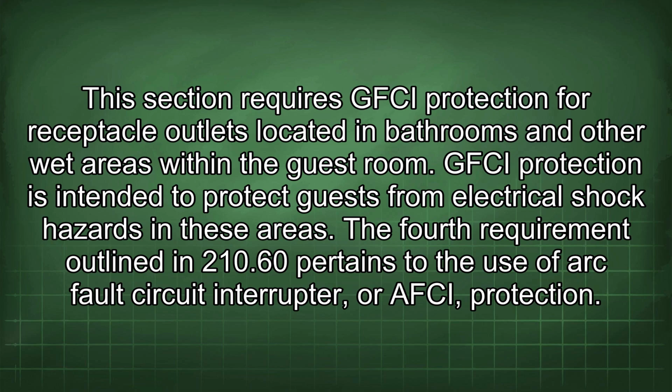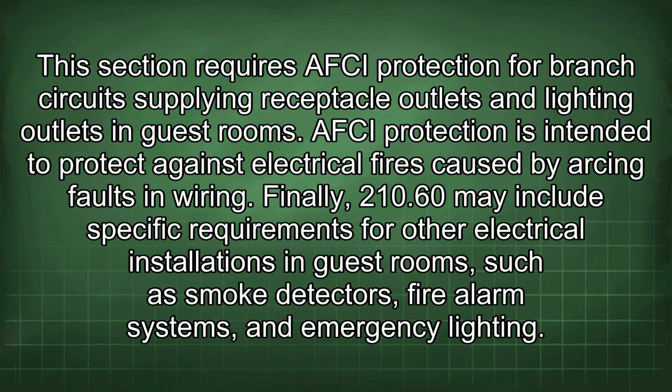The fourth requirement outlined in 210.60 pertains to the use of arc fault circuit interrupter, or AFCI, protection. This section requires AFCI protection for branch circuits supplying receptacle outlets and lighting outlets in guest rooms. AFCI protection is intended to protect against electrical fires caused by arcing faults in wiring.